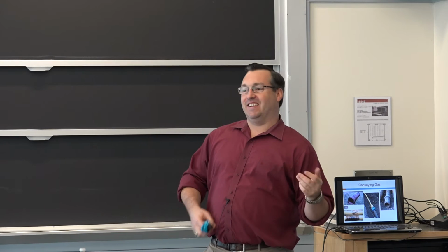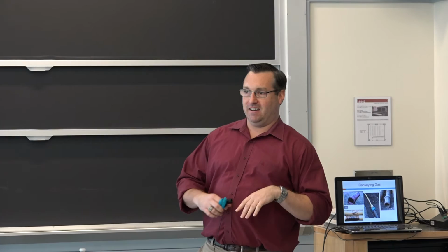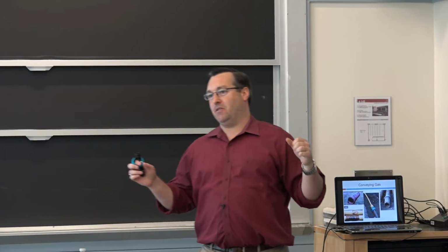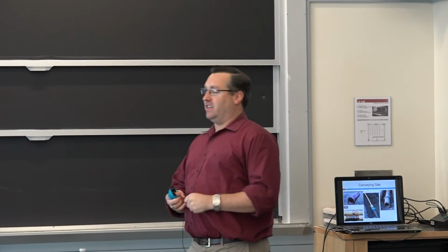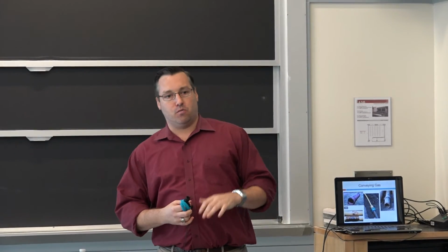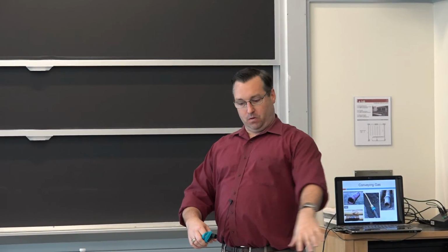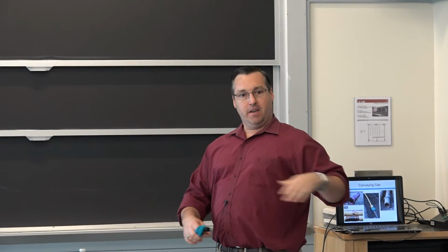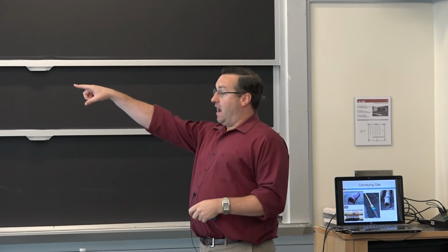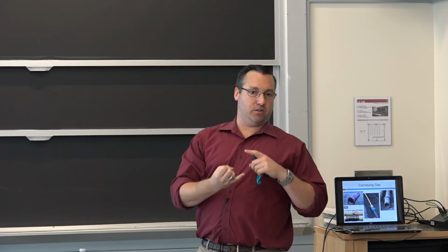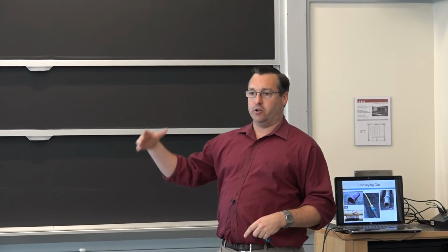When I take the T in, I think of it from a maintenance perspective, and I've worked on train derailments where you actually see the fractured rail afterwards. Some of the interesting things are that with trains, you get a lot of fatigue issues with the rail, because the train truck is running over it. If you think of your train system, you have the rail, then you have ballast underneath, which is your concrete and your aggregate. And that allows water to drain out.